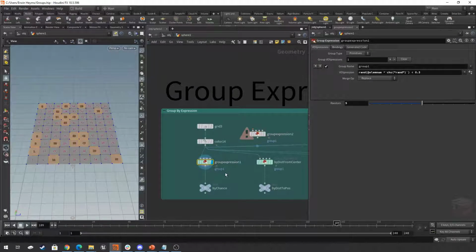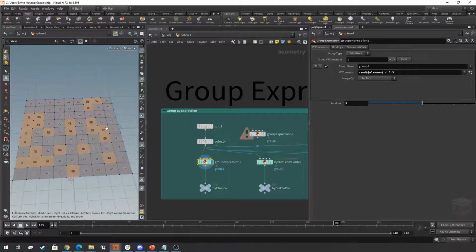I'll go more into what VEX actually is in Houdini later on, but right now let's have a quick look at what this node can do. If we look over here in the node itself, we can see that we have a drop down here on the right, and this allows us to select a particular script that's pre-written and comes with the node. We can also write our own scripts or manipulate it. So right now what I've taken here is the 30% chance expression, and this will select a random selection at 30% on our geometry.